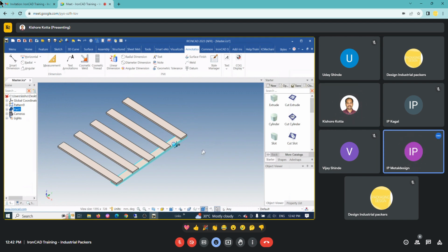If you draw a box directly, then you can select that handle, right click, create parameter, and link it up. Can we do this process again in short? Yes, absolutely.